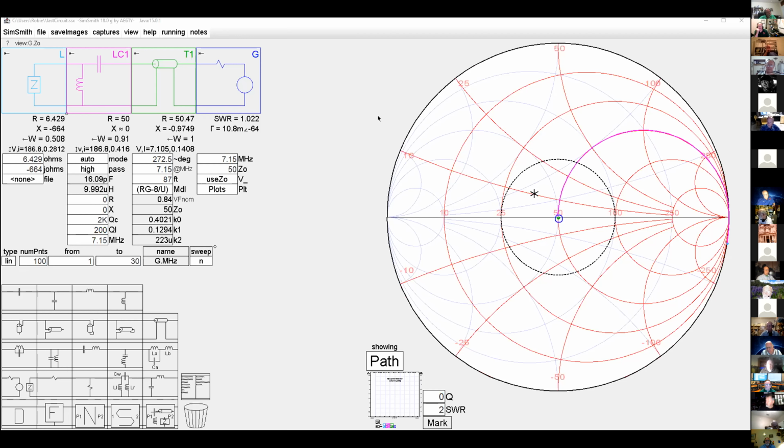Calibrate your VNA, and use a very short length of line between your VNA and your load. Remember what I showed you here about the impact that transmission line has on your measurement, right? Let's say you calibrate your VNA with your load open and short right on the VNA, and you add 2 feet of line. Everything that you measure at the connector of the VNA should be accurate, but if you put that 2 feet of line in, then the numbers you get at the VNA are not the same as the numbers of the actual load. And we just demonstrated that here.